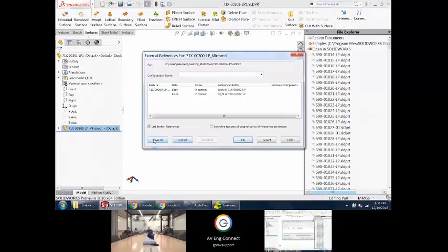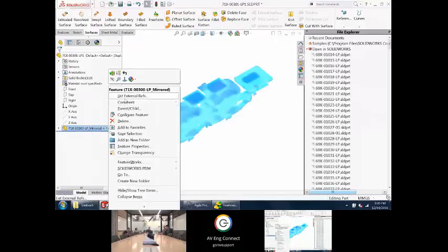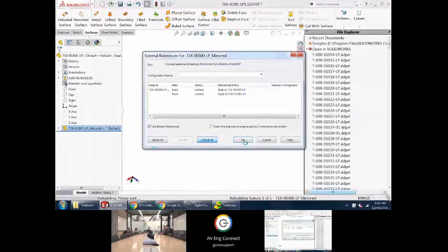So if you don't want an external reference, you can right-click, list external references. There's a choice to lock or break. Lock is nice because you can take it back later. So if I choose to lock the references, what it'll do is it will flag the reference with a little asterisk that lets me know there is a reference, but I'm not going to update it. So if the original changes size, this one still stays the size that it is until I right-click, list external references, and unlock it. So that's the power of the lock-unlock is I can choose, oh, I changed my mind. I want it to rebuild again. And so you can do that with that lock and unlock.